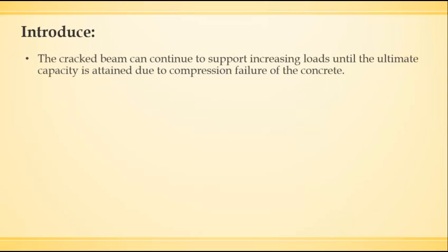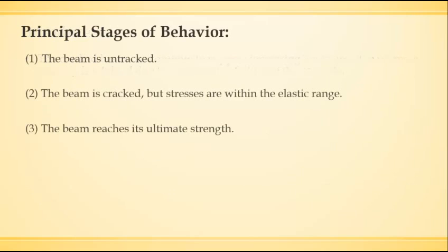The cracked beam can continue to support increasing load until the ultimate capacity is attained due to compression failure of the concrete. There are three principal stages of behavior of beams. The first stage is the beam is uncracked, then the beam is cracked but the stresses are within elastic range, and the final stage is the beam reaches its ultimate strength.